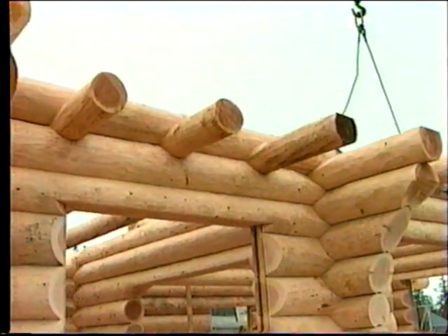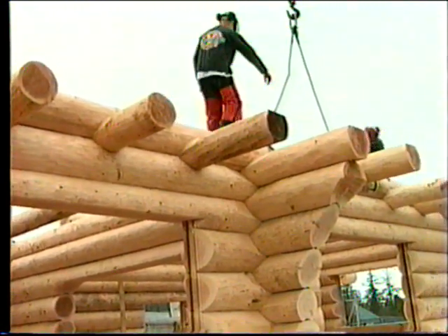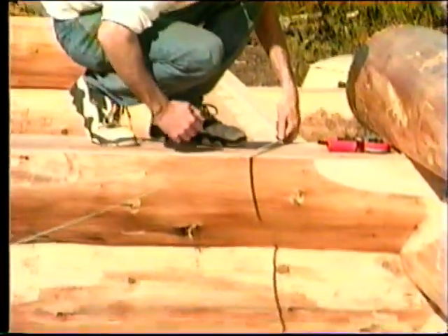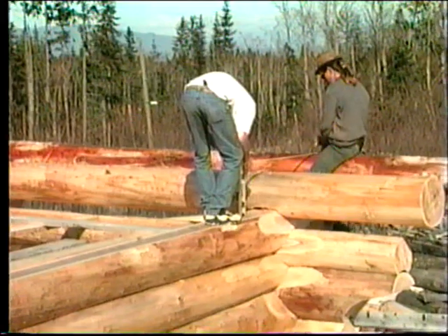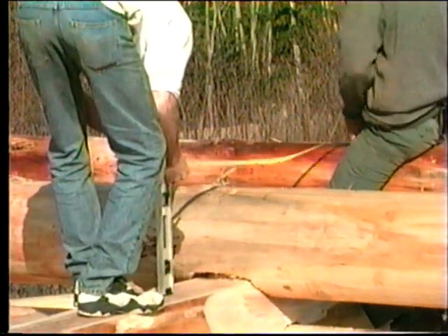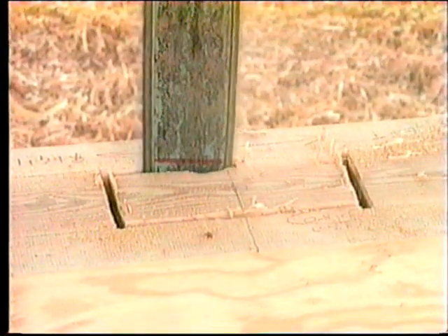Also, you will lay out the flat for the top of the cap log, and if you take the time to check the location of the center lines and square of the building, you can also cut the mortises for the roof structure while this log is on the ground. If you are using an outrigger plate, treat the top log of the wall as a joist and flatten it also.